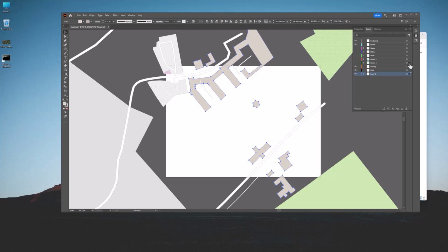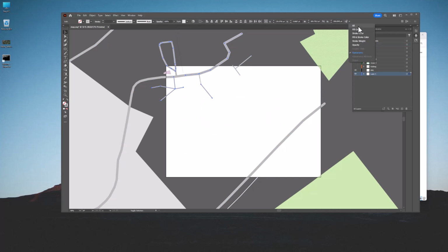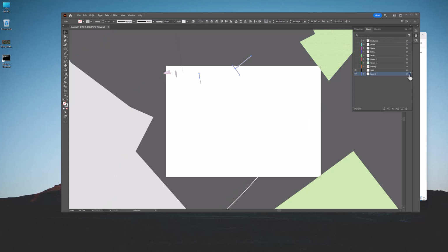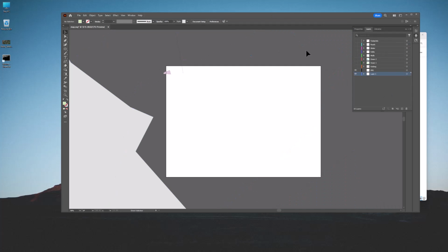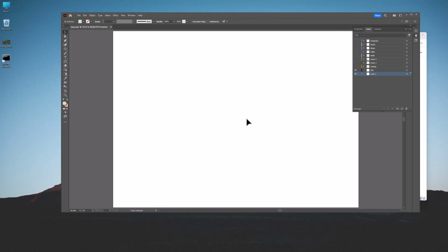And just double check your layers after you have distributed all the line work and make sure that everything is layered correctly, because as you work through, you'll notice there are some elements which are underneath others. So after that, I'm going to zoom out and get rid of any other elements that are unrelated to my site plan. I'm just deleting them, and then I hit Control-0 to bring my artboard back into view.